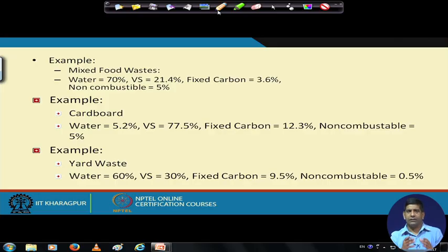when you heat things up, usually the waste to energy plant works at around 1000 to 1200 degrees centigrade, so as not to have some of those air pollutants like PAH, polycyclic aromatic hydrocarbons, and some of the dioxins and other compounds that are produced at low temperature. So we try to work at high temperature to reduce the amount of air pollution coming out.